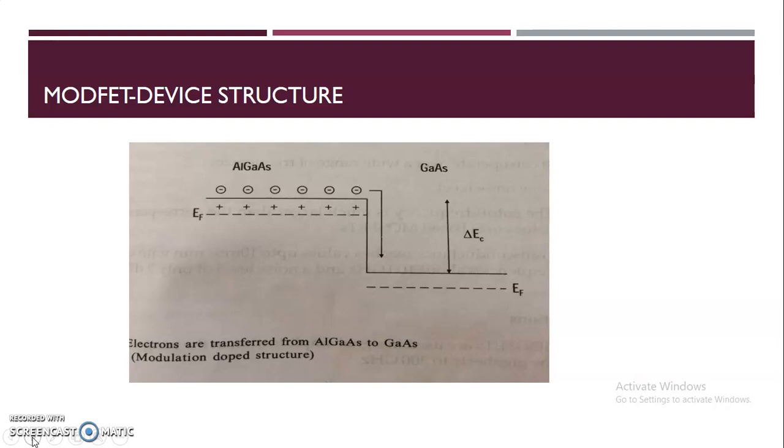So the undoped layer as spacer signifies the effect of the MODFET. It isolates the conducting electron channel from the N-type layer that generates the carriers. It leads to higher electron mobilities due to reduced interaction with the ionized donors. The width of the intrinsic layer is about 5 nanometers.